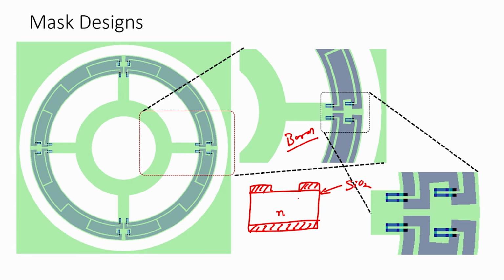One is a solid way, another is liquid, and the third is with the gaseous phase. We will use the liquid phase just for this particular class, and in that you can spin coat this boron on this silicon dioxide, or oxidized silicon wafer, with a window that you can see. Now, after this you have to,